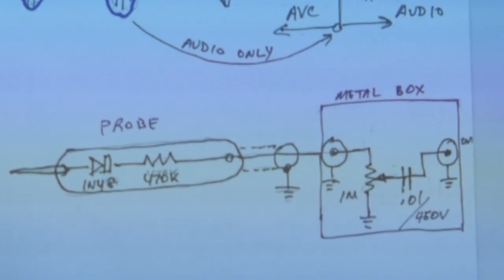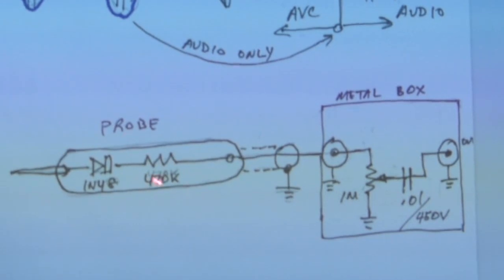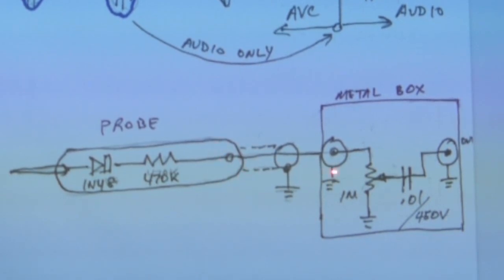Get even a pen case and stick a nail out the front end or a needle, glue it into place, couple your diode, and there's a dropping resistor here. That's 470K. You might have to adjust that for your particular circuit. And then have a little metal utility box in which you connect with a coaxial cable into your input, and